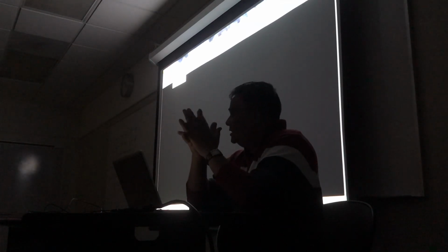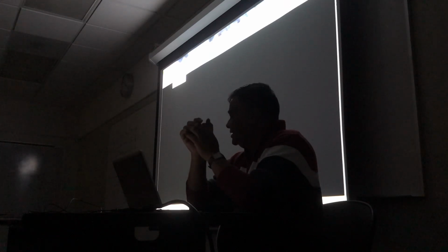Okay, so what we are going to do here is model a typical floor first. Then we will copy that typical floor for the first floor, and if we have time, we will change it. If we don't have time, we will not change it. The first floor has different loadings. Usually they have a lot of storage. The corridor live loads are different. That's why we will change it. And also at the roof level, we can change it because roof live loads are also different. Okay? So let's do a typical floor first, and then we'll see.